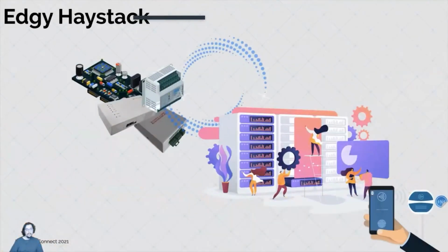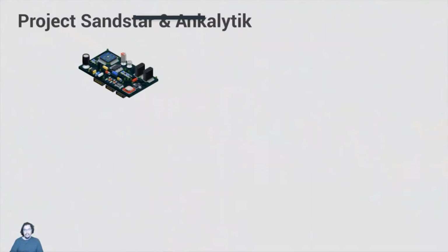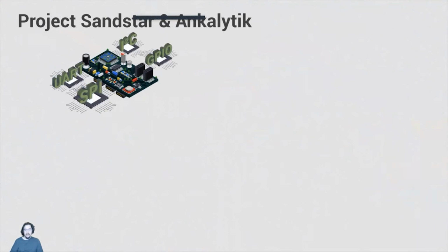The other side of the spectrum of the edge is the controllers, the equipment. So for the controller EAC V1, we have built these EAC IAQ, and we have EAC Modbus. The Modbus device has isolators on it for the RS-485 ports. They all run with Project Sensestar. So Project Sensestar is basically in electronics boards. There are protocols like I2C, UART, GPIO, SPI.